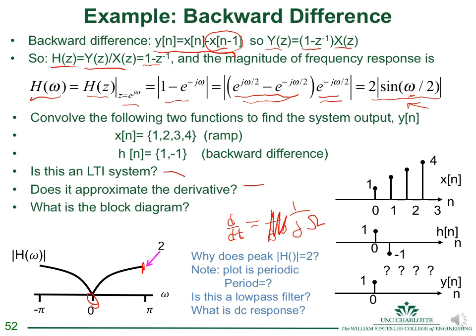And we see that the discrete time Fourier transform of the backward difference has kind of the same basic properties of a derivative, in that it has 0 response to DC. Of course, if I put a DC voltage into a differentiator, the output is 0 because the slope is 0 on a DC line. And so this backward difference, which measures change, acts a lot like a derivative.